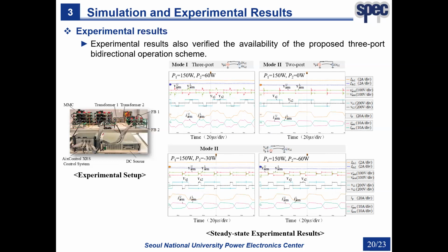The upper right figure shows the result when the transfer power of port 2 is reduced to 0. It can be seen that its AC side voltage duty cycle is controlled to 0, and SST realizes a 2-port operation.